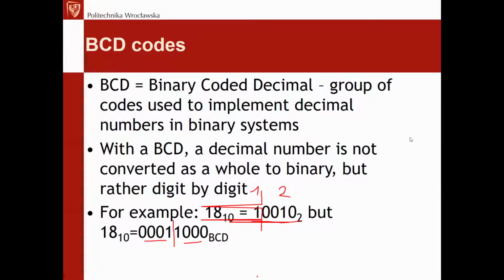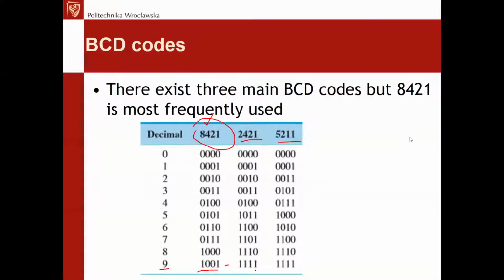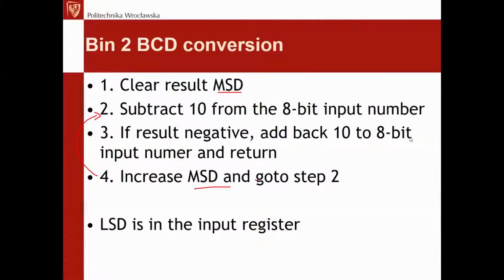quadruplets here. So we can have, of course, any number, and we can have the BCD which is 4 digits long or 6 digits long. Then naturally this algorithm must be modified to include subtracting of 100, of 1,000, and of 10,000, for example, if the number is to have many digits. The BCD number, for example, that we want to convert. Anyway, this conversion is a division-less conversion, and that's the advantage.